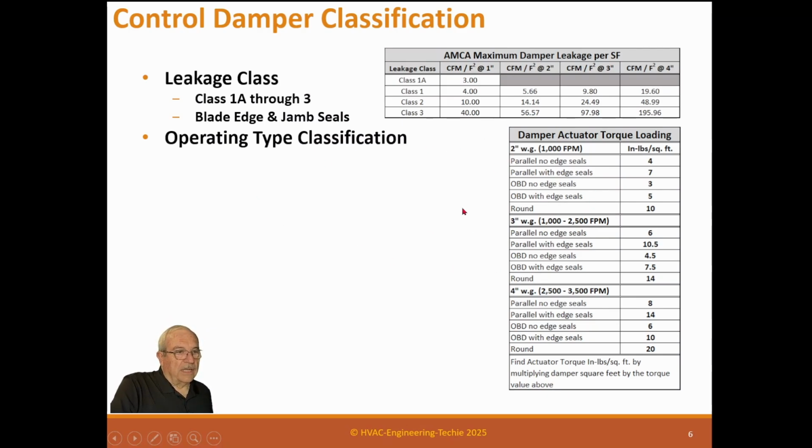And that's what a control contractor needs to do, is put the correct actuator on the damper. We're talking electric actuators here, but if you have pneumatic actuators, it's slightly different because the pneumatic actuators are always fail-safe. They have a spring, right? So as they open, they're pushing against a spring, and when you stop it, then that spring will run it closed.